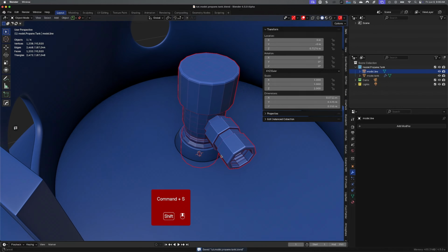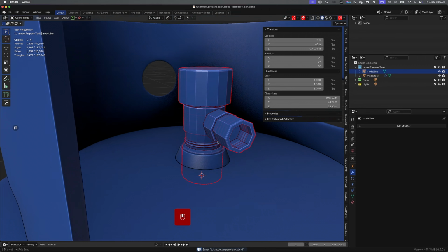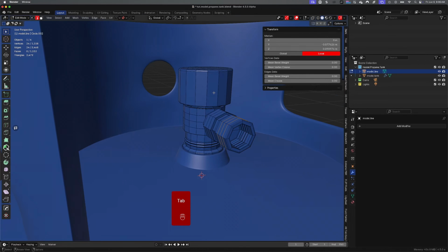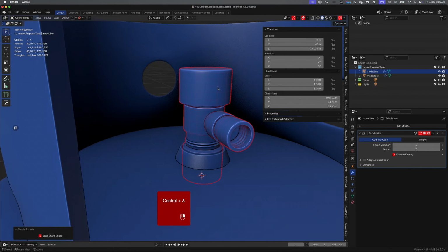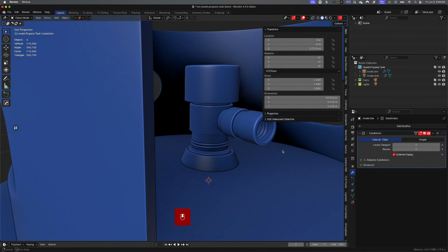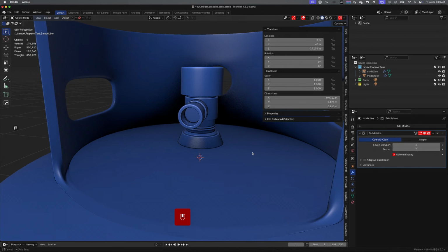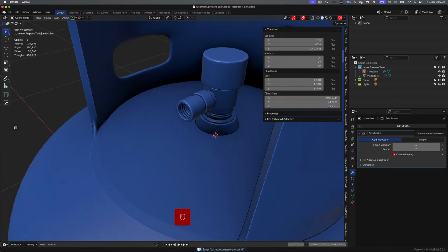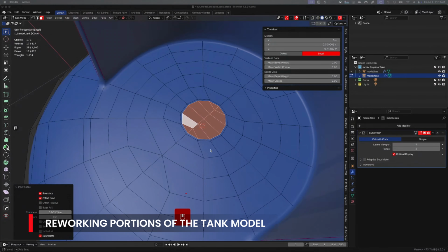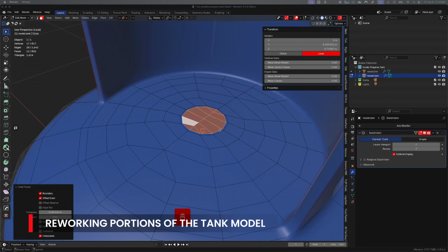Now watch. We save the file. Let me do some more support loops up here. And I'm going to run a level 3 and a shade smooth. And bam, look how clean that is. See, by doing that extra work, your bevels and everything, and make sure everything's good, when you run sub D the first time, you'll nail it.